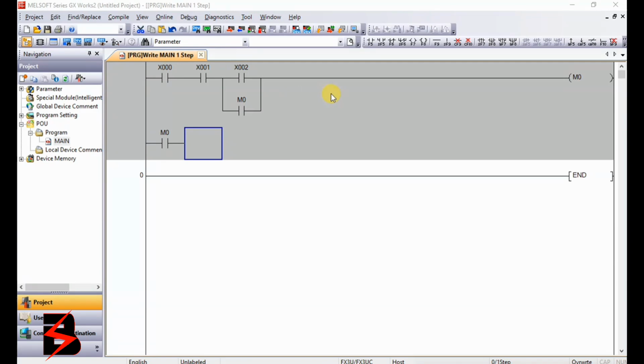After that, I'm going now to use instructions. I'm going to use here a compare instruction. Come here to F8, that is instructions. You click. So I'm going to use a comparison and operator equals. So I'm going to say equals K1. Remember, in our sensors we have three figures. We have 1 for blue, 4 for green, then 7 for gray.